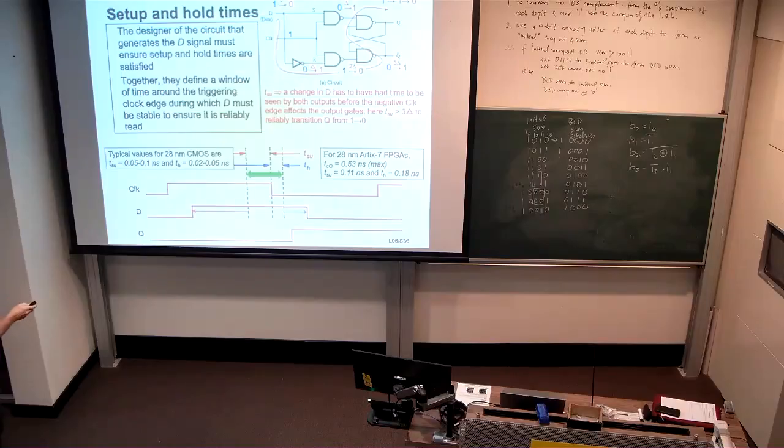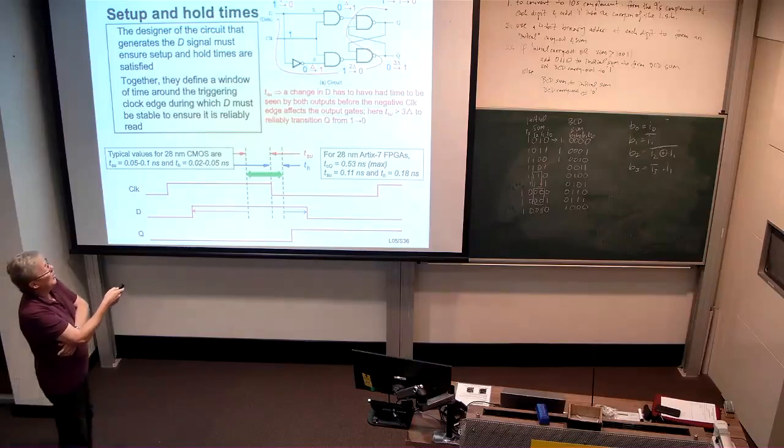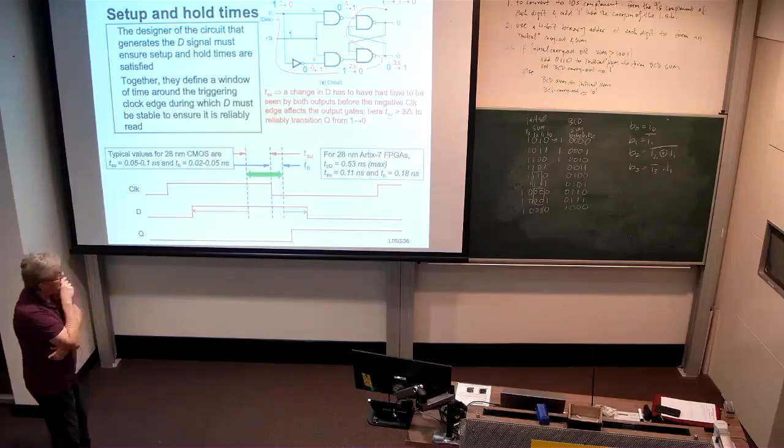Then the configuration of the circuit implies that the R wire is going to change from 0 to 1 at delta time due to the delay of the inverter. And we're also going to have the output of this NAND gate up the top here changing from 0 to 1 at delta time because D has gone from 1 to 0. Okay.